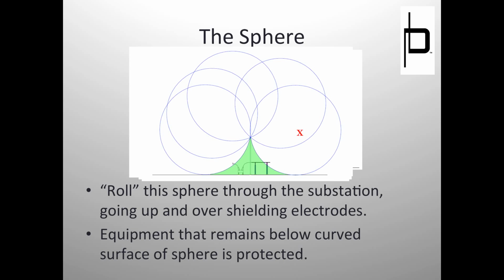The fixed angle method is great and is still used for protecting buildings, and things where your mast heights are 2 feet, 3 feet, things like that. A lot of folks still use it, like I said, in transmission lines where the height of your shield wire is a handful of feet taller than the height of your transmission line. Okay. Sorry about that tangent, but getting back to this.